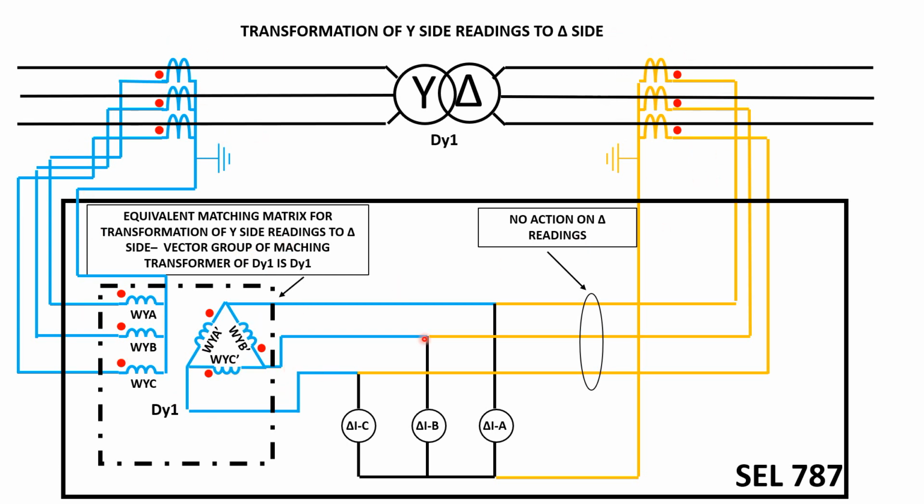And that's why I drew in two different colors. These readings here, the blue readings up to here, are where the relays are located. And this reading is orange, and comes again to this point. If these two readings are in the same direction, then nothing goes to the differential relay.